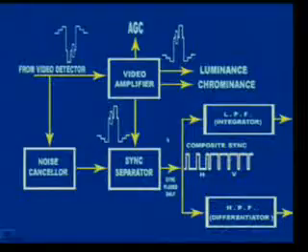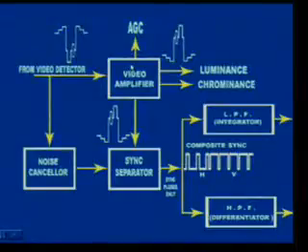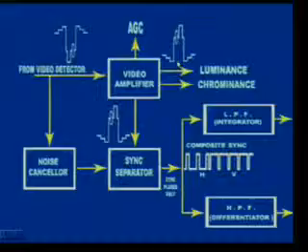Let us come to the video detector and the video amplifier stages. I have already told you that the video amplifier is required to raise the signal level. It has also been explained that as and when any input signal passes through any amplifier, it develops a 180 degree out of phase signal.